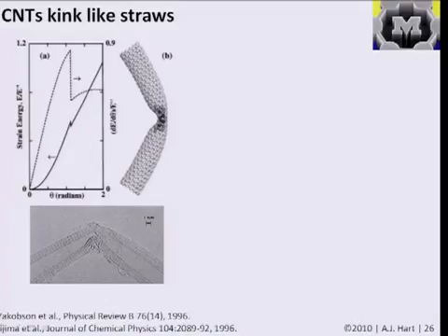And also there is analytical atomic scale modeling where you can see that there is this kind of instability that happens as you bend the nanotube. They're defining this angle theta. Then it snaps over and relieves some strain energy by buckling and kinking like so. And it turns out that people have shown computationally that when you kink the nanotube, in some places the atoms actually reorganize. They will move around to relieve strain energy, and when you unkink it, the atoms move back. So this is kind of like a reversible deformation of a little nanoscale structure.